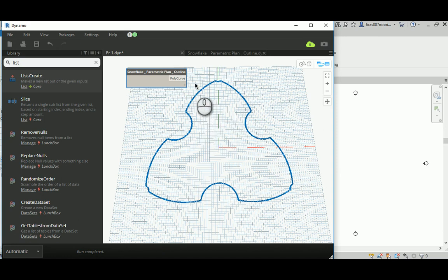It's okay if the dimensions are fixed, but we are not going through all this painful process of making a Dynamo custom node and a full function just to do this once. If we are doing this once, we shouldn't go and make it a custom node, right? And the custom node now provides only one output that allows us to have the results. There are no inputs, which is really a bad thing.